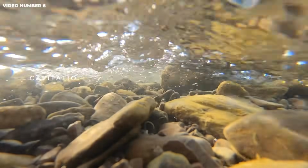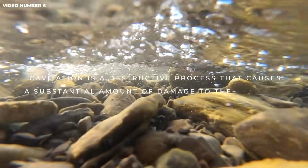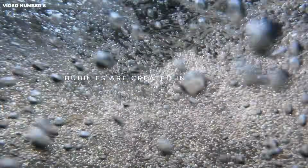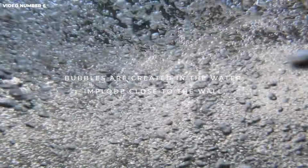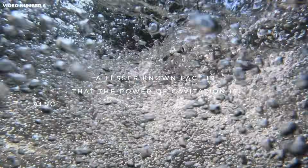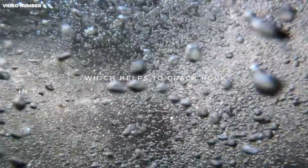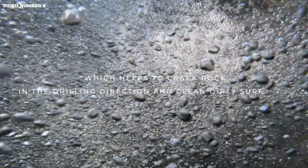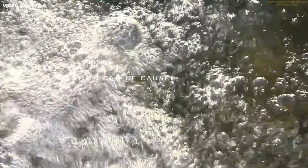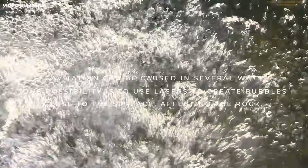Cavitation. Cavitation is a destructive process that causes a substantial amount of damage to the turbines. Bubbles are created in the water, implode close to the wall, and create significant local pressure. A lesser-known fact is that the power of cavitation is also used to improve the drilling efficiency, which helps to crack rock in the drilling direction and clean dirty surfaces. Cavitation can be caused in several ways. One possibility is to use lasers to create bubbles close to the surface, affecting the rock.